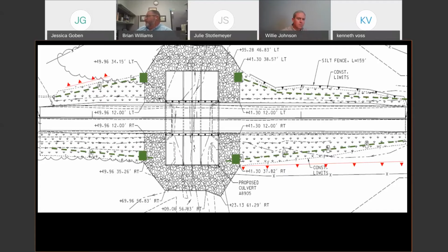So we need the new ditch lines, as you can see, where the original rock ditch checks were going. That's got to be the new ditch line, right? So there ought to be sediment traps out in each of those quadrants, as well as maintaining that existing silt fence that we had from the initial EMP phase.